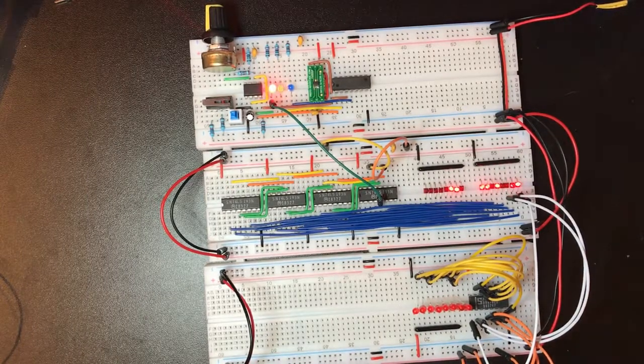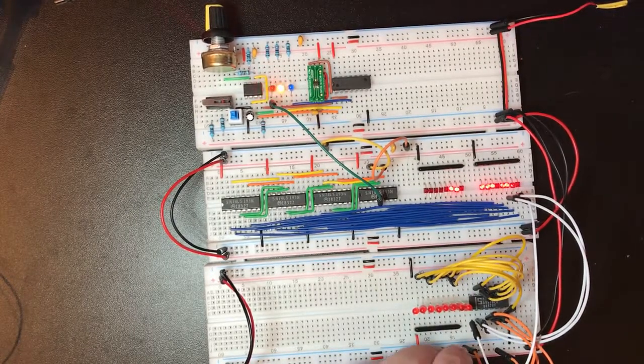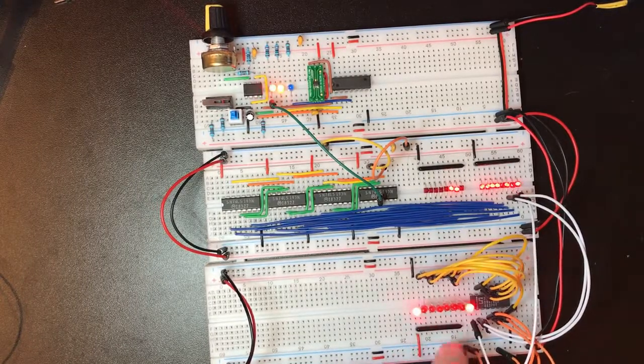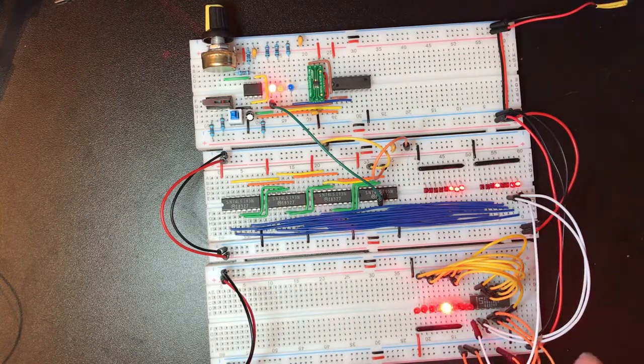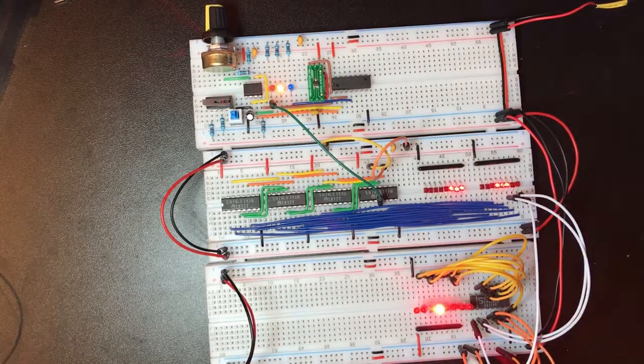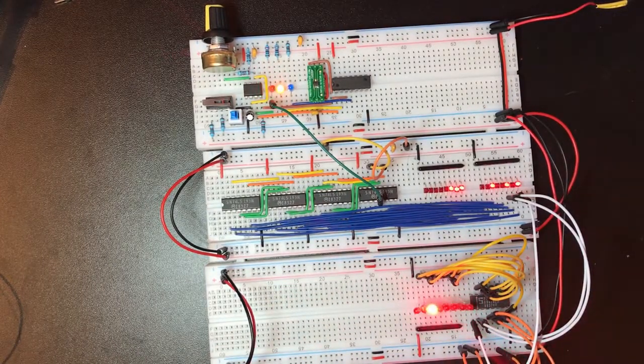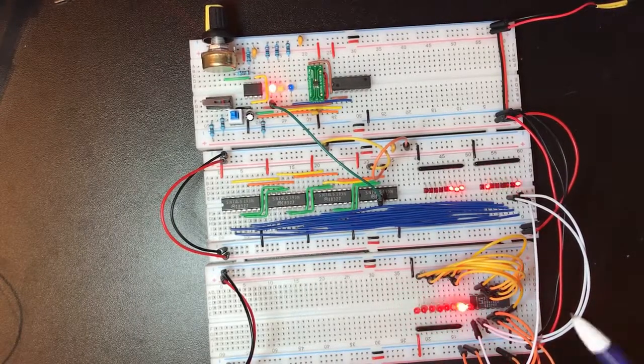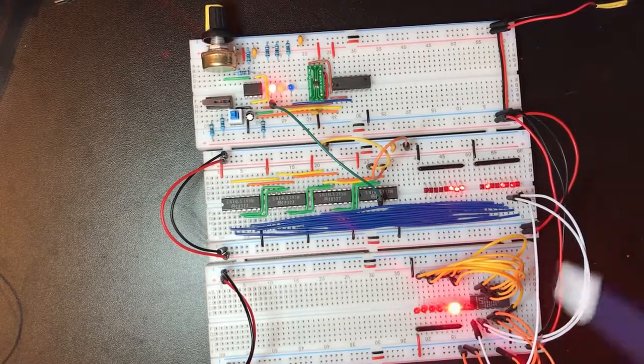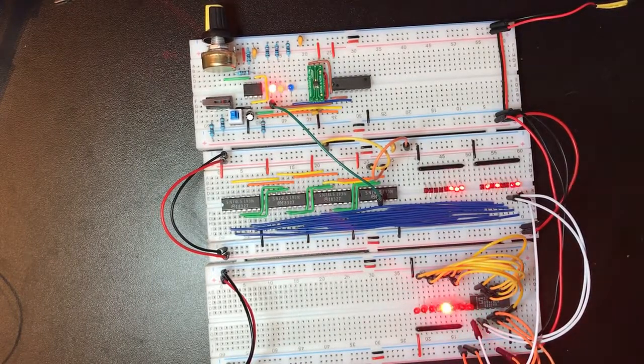Another possibility is if we were to say not have 8 registers on the bus, we had 7, we could simply have one of these lines not wired to a register. So there would be a safe value, maybe 000 or 111. So one of the LEDs at the end in this wasn't going to be used for loading. So we've got a variety of different ways of doing it. If we don't have 8 registers, that's probably the easiest way of doing it, because that means we still just have 3 lines and we can drive up to 7 registers.